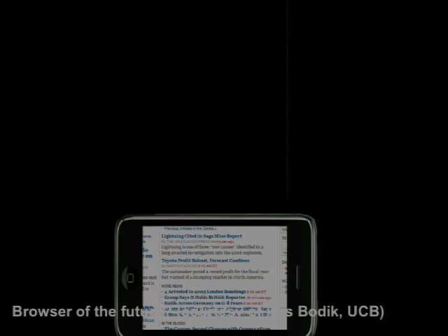What they're really measuring, remember, I showed you a picture last time of a silicon accelerometer, which has a silicon substrate with some ridges and then suspended silicon fingers. When you accelerate in one direction, the spacing between these changes, but also when you tilt.